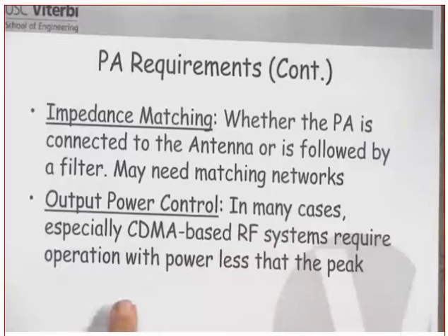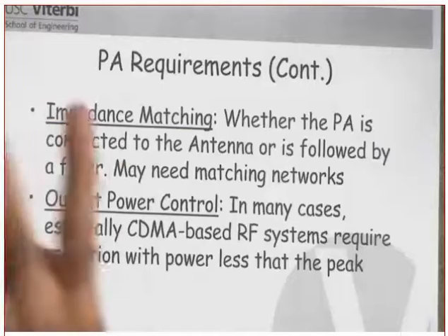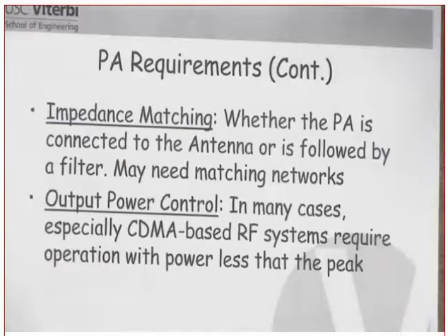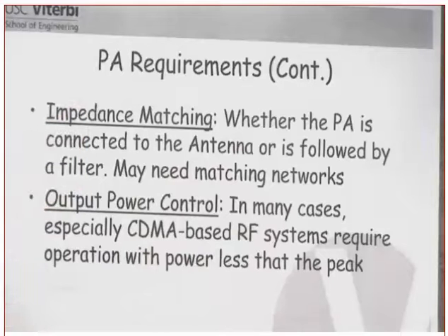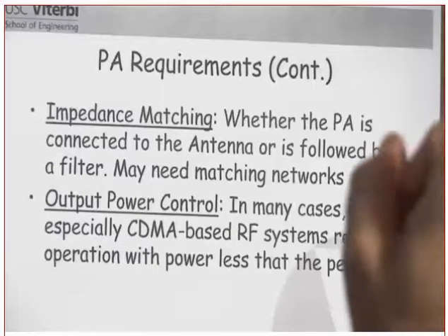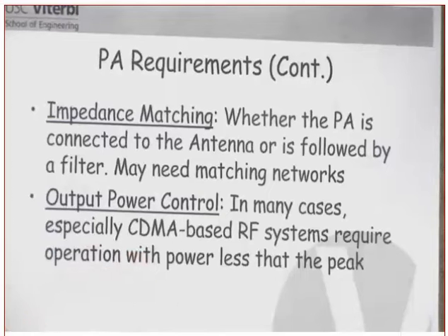Why? One more time. In CDMA, all those mobile devices are transmitting at the same time using the same frequency. Are you following me or not? You need to apply a power control mechanism so that the receiver, for a mobile unit that happens to be close to the base station, does not overwhelm or block the receiver from sensing a signal from a mobile that happens to be a little bit farther away from the base station. We discussed this earlier in the semester, if you remember, which I doubt. Did you get my point or not?